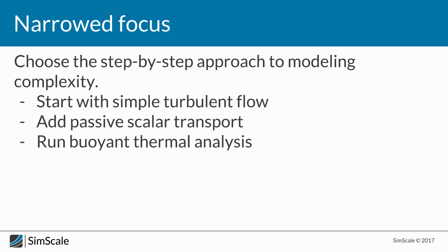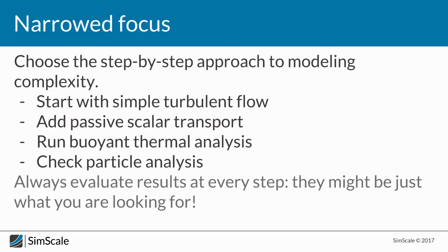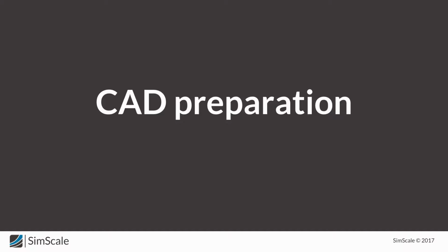When this is done, we can move to increasing complexity, like adding buoyancy terms and heat transfer into the problem, or checking particle analysis to track where they are going. When moving through these steps, we should always evaluate the results that we're getting at each one of them. It might happen, and it very often happens, that the results you already get with a simple analysis will be just what you're looking for and be enough to provide an insightful engineering decision on improving the design of your clean room.